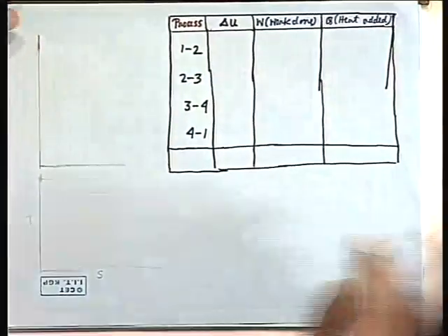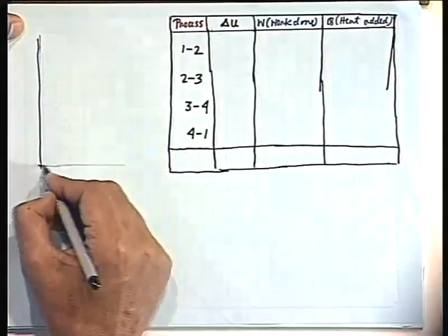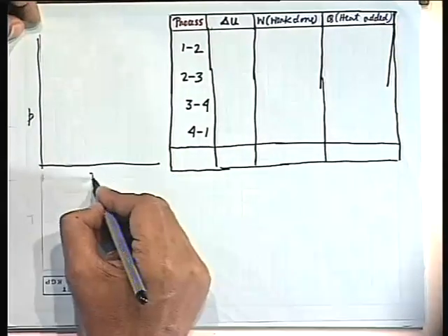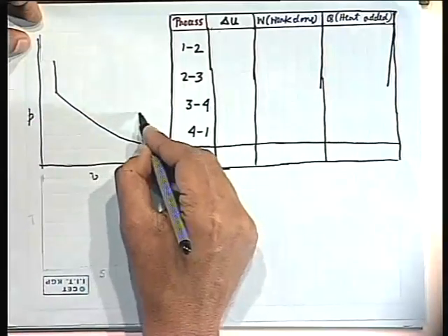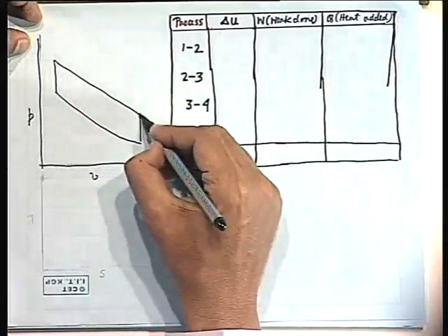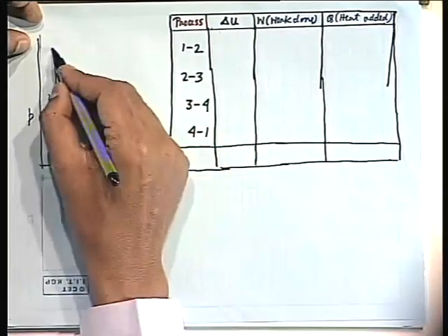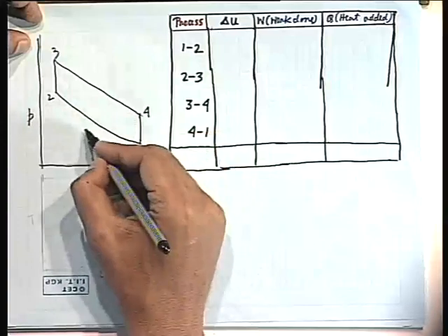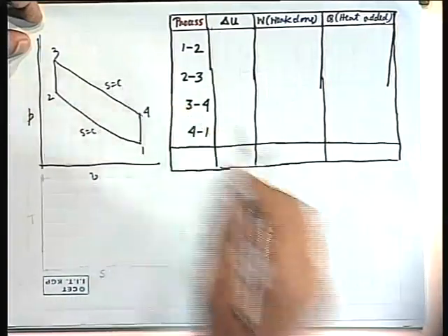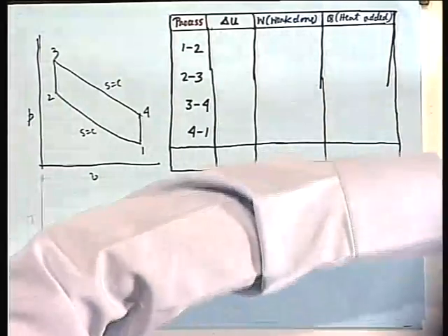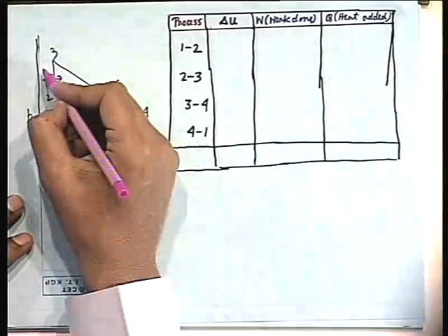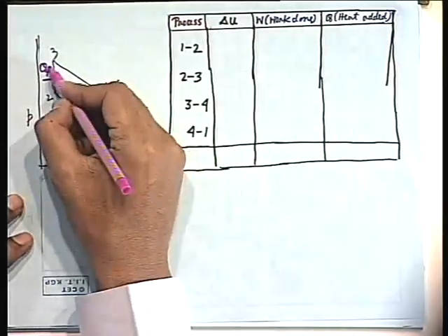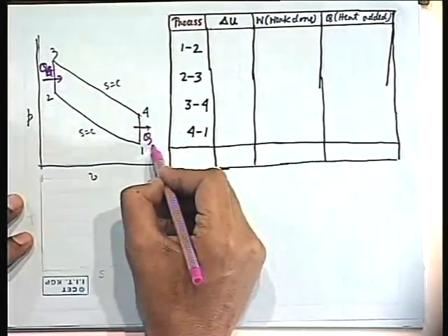So the rest is now a routine part. Now I again draw the PV diagram of the Otto cycle before doing our routine job. So this is like this. So this is 1, 2, 2, 3, 3, 4. So this is S is equal to constant, this is S is equal to constant, and we see that heat transfer takes place only in these two processes. That means in this process heat is added, QA, a small a also dq, and in this process QR, heat is rejected.